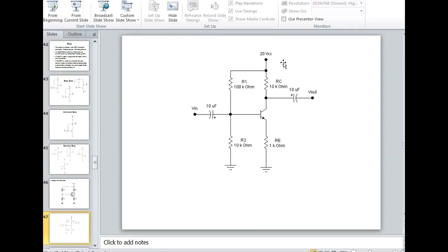Now we come over here, it depends on what I'm hooking this up to. I'm hooking this up to a resistor. The resistor is connected to common. So right now, of course, later on, guess what we're going to do? We're going to hook it up to another amplifier. What we usually do when we do amplification is we like to go through stages because the more gain one amplifier has, the noisier it is. So usually we go through multiple stages.